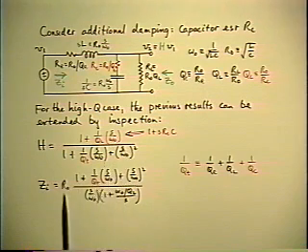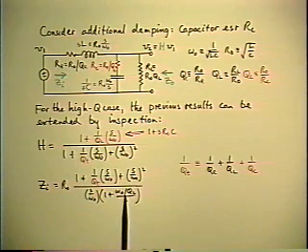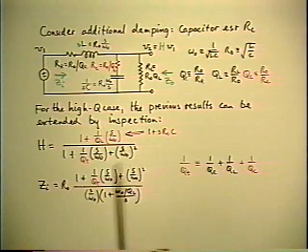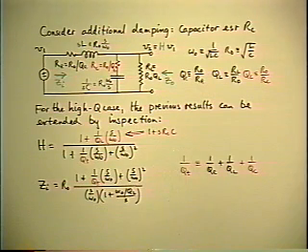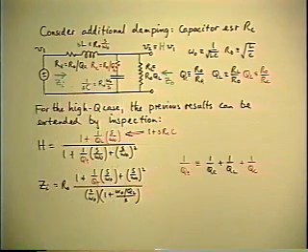So again, you can build a quantitative result by extension or extrapolation. I'd like to say inductive reasoning, but that word unfortunately gets confused with the physical inductor. But anyway, it's an extension of the reasoning without actually doing the algebra. Notice again the usefulness of the symmetry between normal and inverted poles and zeros. That's what enables you to make these arguments to do with zero frequency asymptotes as well as infinite frequency asymptotes, which covers all the possibilities.